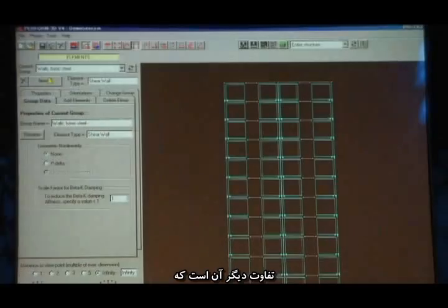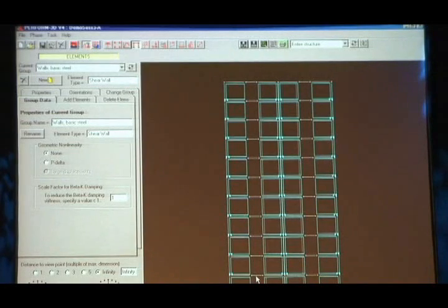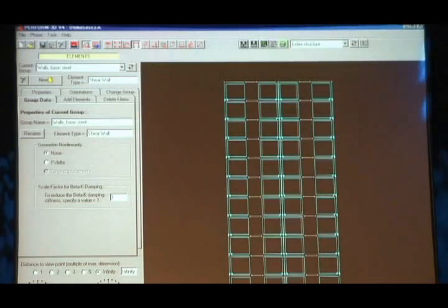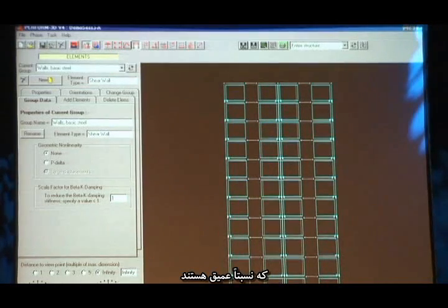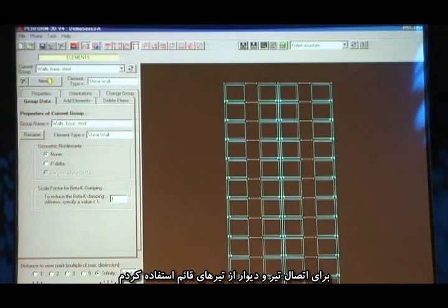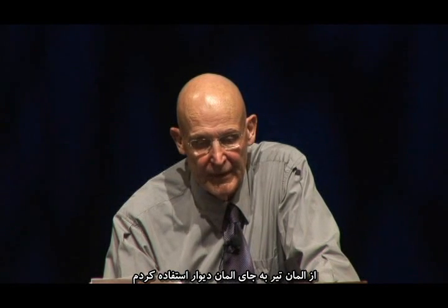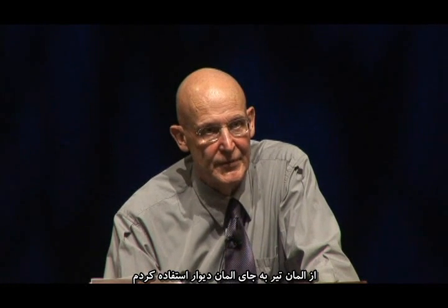And then the other difference was that for the upper beams, I used horizontal embedded beams. For the lower beam, this is a pretty deep beam, I used a vertical beam to connect the coupling beam into the wall. But in all cases, I chose to use beams rather than wall elements. And I'm inclined to think, in general, that's something I'd do. You've got better control over the behavior if you use beam components for coupling beams rather than wall components. Does that answer your question?